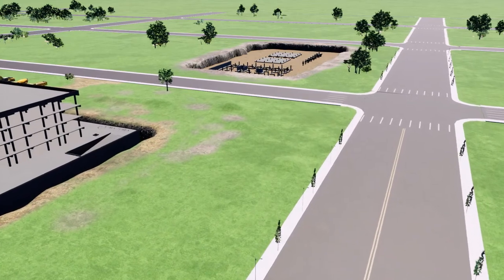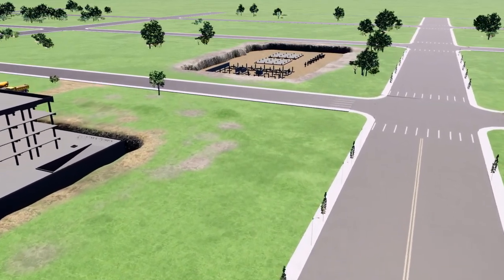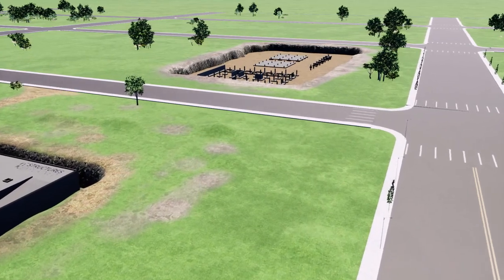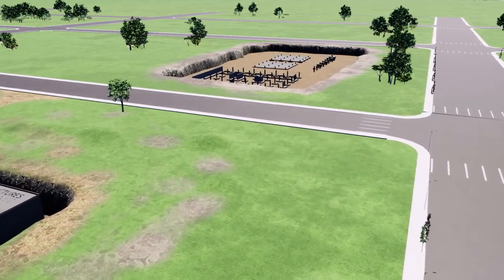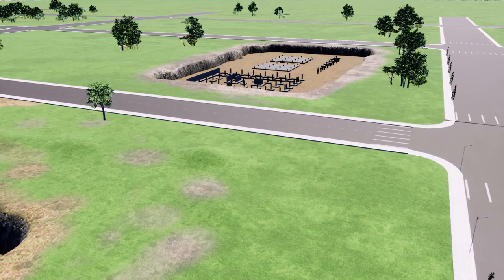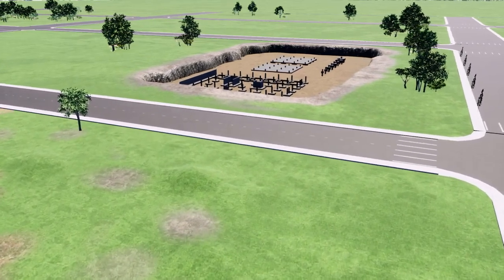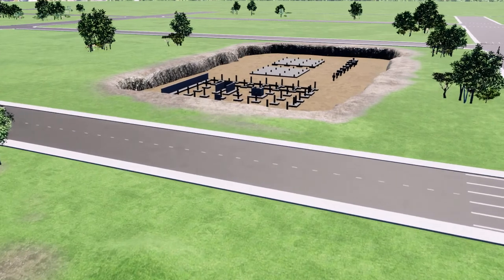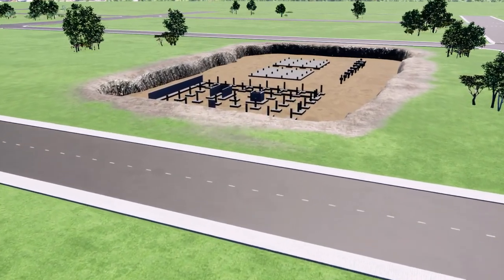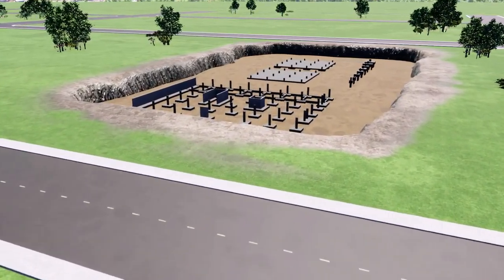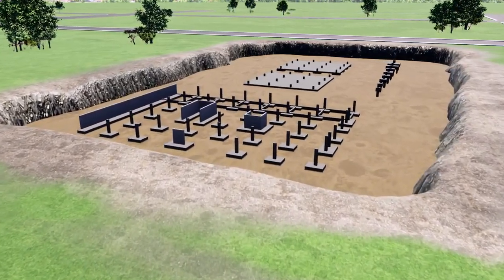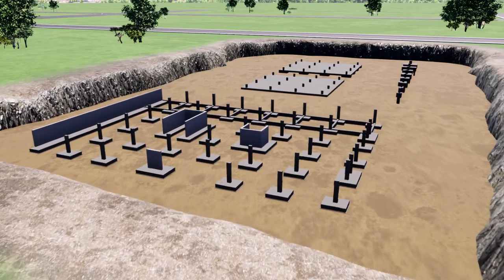Various factors play a role in selecting a suitable type of foundation for the structure, such as type of structure, condition of the soil at the location of construction, other surrounding structures, water table below, property limits, and many more depending on site conditions. Once the foundations are laid for a structure, it is very difficult or impossible to repair or inspect them for structural damages. Hence, it is very important to select or design appropriate foundations.